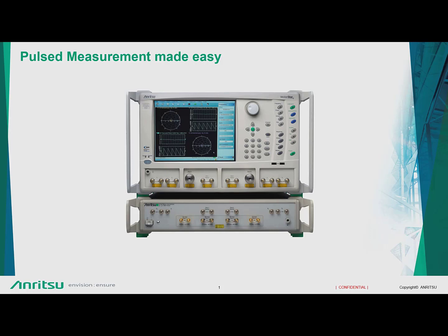We will be touching upon how biasing is handled for RF or DC and IV, what the various applications on wafer are, and what the relationship between time and frequency domain is when making pulse measurements. We will also be showing you key pulse parameter measurements like point in pulse, pulse to pulse, and pulse profiling as